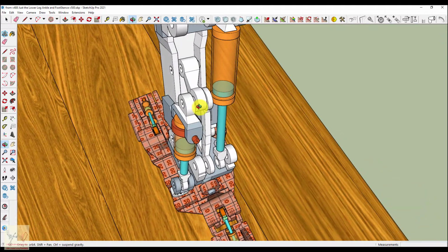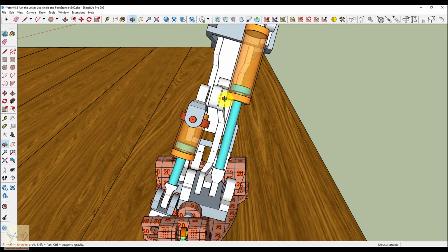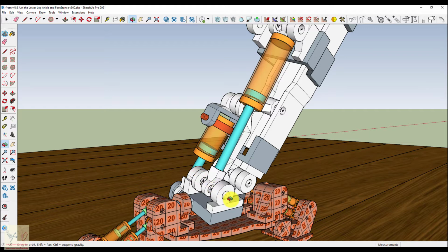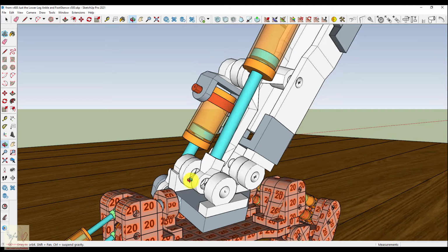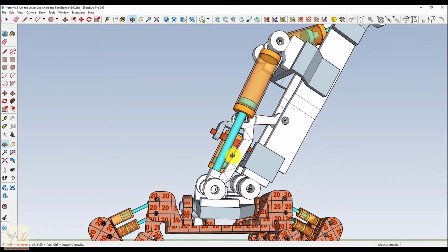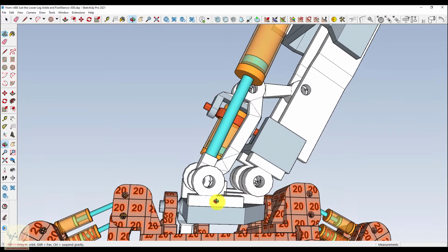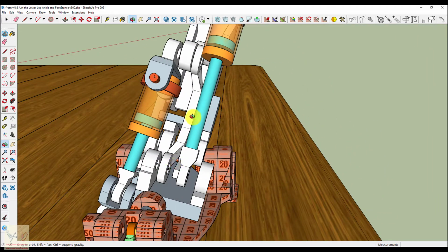And the interesting thing about this swing arm is that it is connected by another connecting rod to the shaft that is the pull point or the push point for dorsiflexion and plantar flexion. And so what happens is when you send a command to the dorsiflexion, plantar flexion piston, and it lifts up on this plate to cause dorsiflexion or plantar flexion, when it moves this plate around, it also moves this linkage arm.